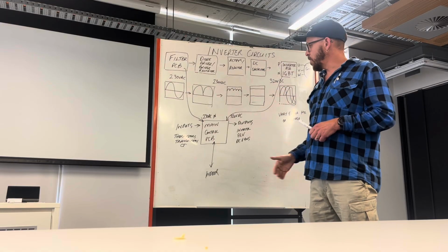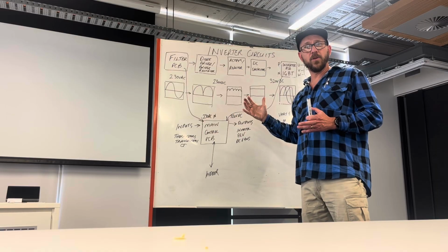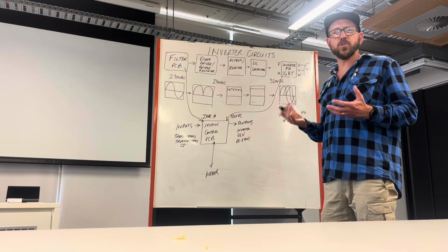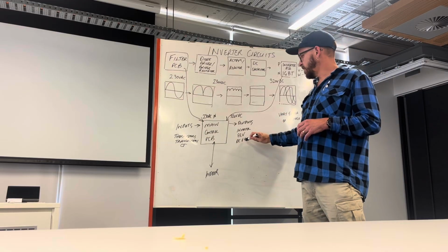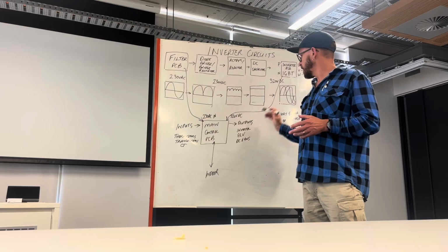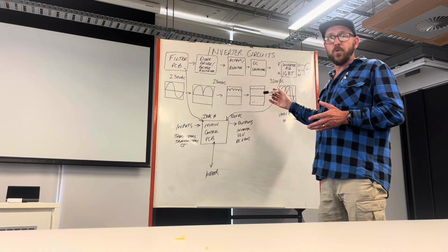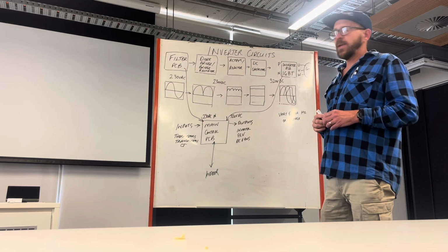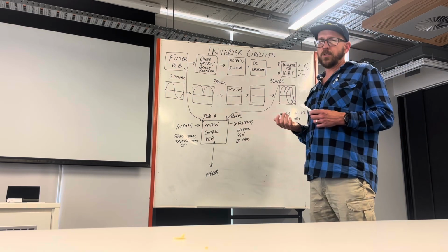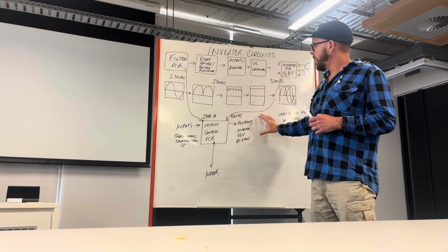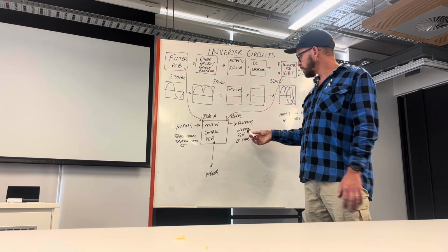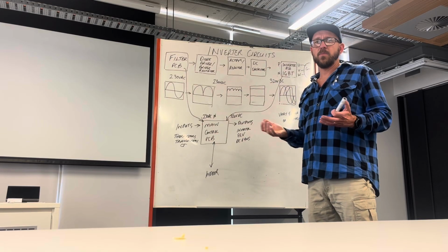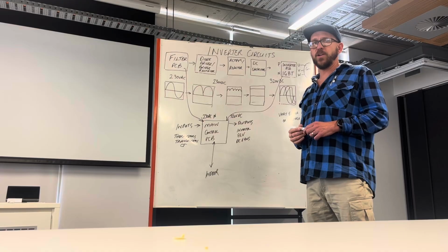If you've got it all in one board and you've got no comms coming out of that unit, then you know that outdoor board's failed. You need to look at what's caused it to fail. Has a DC fan taken out the board? Has the compressor shorted and taken out the board? Or has the board just failed? Maybe it's got a mouse or a gecko in it. Maybe it's had a power spike. But knowing how to test these components and what voltage we're expecting, hopefully this is going to help you fault find units in the future.